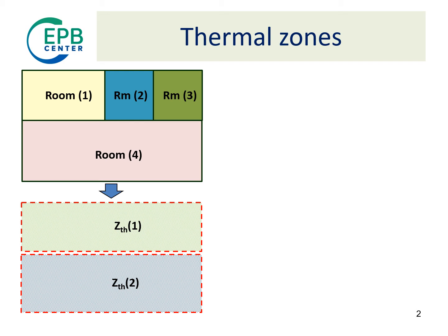For the calculation of the overall energy performance, combine as much as possible spaces into one single zone. By preference, one thermal zone per building. In this example, we have two thermal zones. Default rules are given where and when partitions are needed, and they can be replaced by national rules.